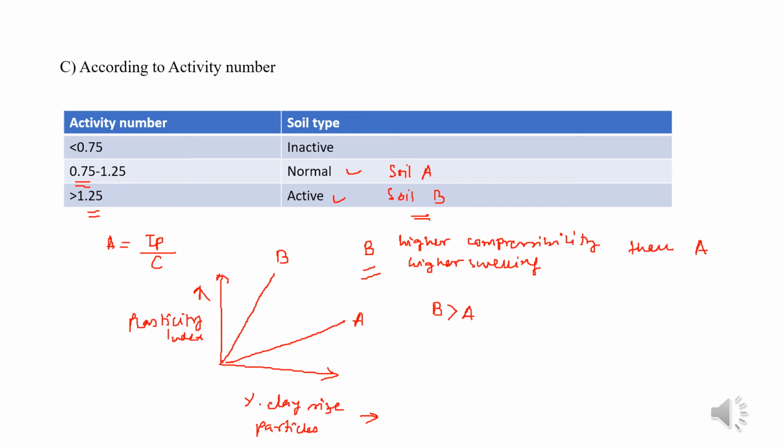This is because both the Atterberg limits and engineering properties correlate well and are influenced by the same set of factors, such as the natural structure of a clay soil, the pore water, or the history of the soil deposit. So the use of the indices and the consistency limits is very important. We talked about the activity number, and judging on it we can determine the compressibility and the swelling characteristics of the soil.